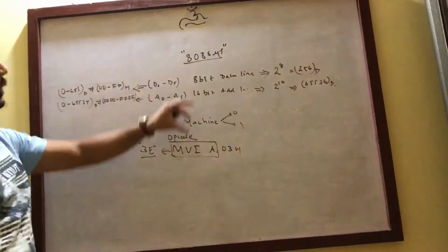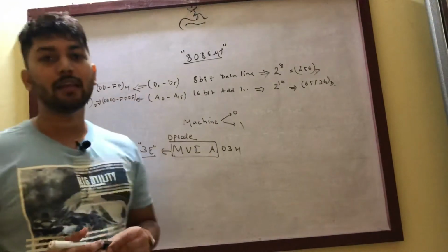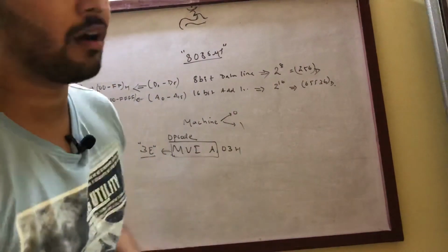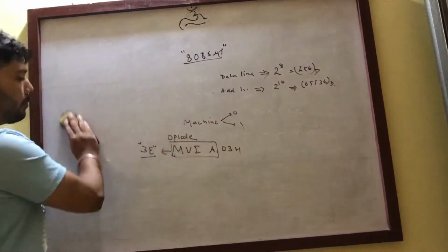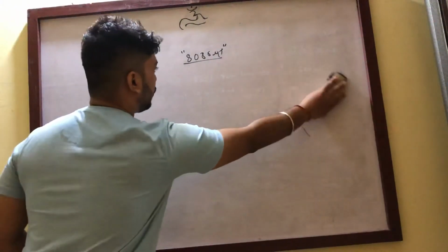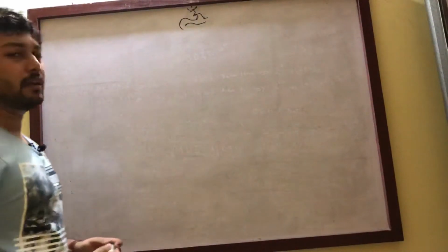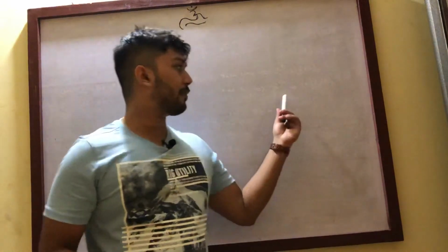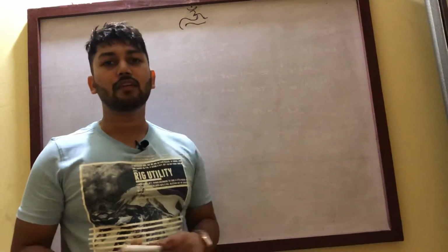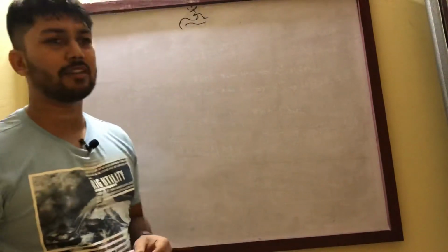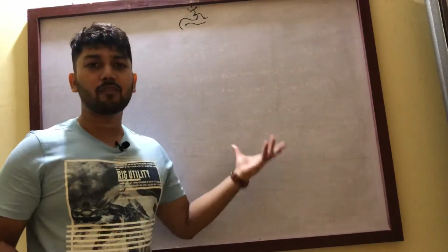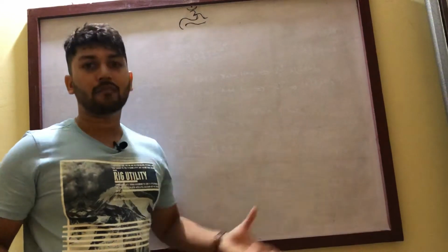So this will be the basics of the 8085 microprocessor, and let us start with a basic program, say addition of given 2 bytes. I hope you are familiar with the addressing modes used in the 8085 microprocessor. There are basically 5 types: immediate data, for which I've given the example of MVI A, then direct addressing mode, indirect, implied, and then register addressing mode. In the example itself we'll understand and distinguish the different types of addressing modes.